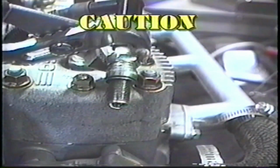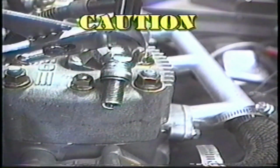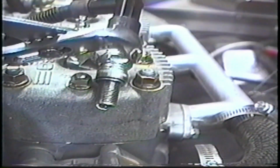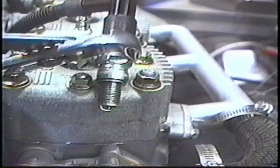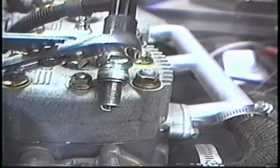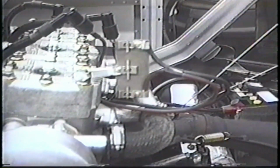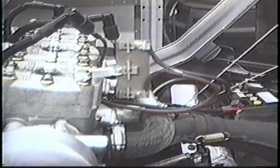Caution: when checking for spark, never lay the plug near an open spark plug hole. The spark may ignite fumes or raw fuel escaping from the open combustion chamber. You can also check spark with an approved spark tester. A 2-cylinder engine should be able to jump a 1/4 inch air gap. 3-cylinder engines should jump a 1/8 inch gap.